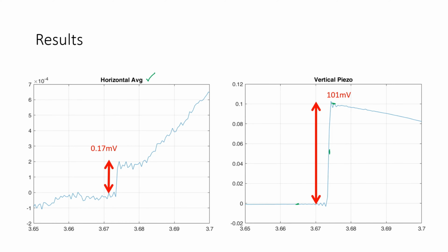The values are numerically given to us, and the next thing we have to do is calculate the ratio between the transverse and the vertical directions, which is given here, and we need to multiply by the sensitivity of the accelerometer in the vertical direction. This is exactly that sensitivity value. We call this S3, or you can also call this S vertical.